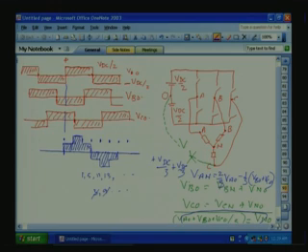Because triplen order, if it is there in the phase voltage, all the triplen order will be in same phase and there is no return path. So, that current will not have a return path. So, current is not there. So, in these voltages, the triplen order won't be there. The triplen order will be dropped across this point, neutral and the O.